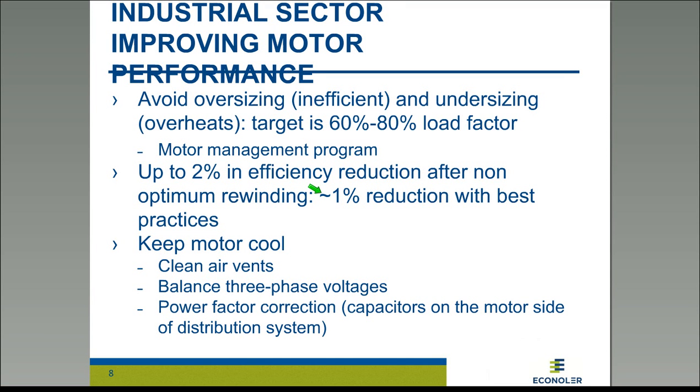In fact, last year we concluded a study where a Chinese laboratory even tested replacement of the stock rotor of motors during a repair activity with a copper winding core. And this allowed the motors to perform even better than their nominal efficiency before the repair. So in fact, with proper technology, it could theoretically be possible even to increase the efficiency of stock motors during repair practice to match or almost match the efficiency of newly manufactured products.